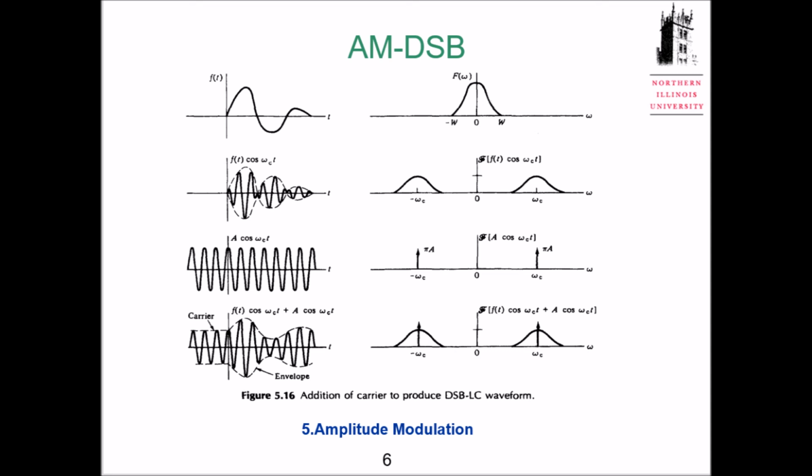We have the picture, we have the figure. If my signal is something like this and its spectrum, F omega, is something like this, like a bell. So I have my signal, the modulating signal in time and in frequency. Here, the signal is mixed with a sinusoid. So here, f of t times cosine omega c t we can find, right? I still have my sinusoid here. However, the envelope is changed according to your message. So this is what happened in time and in frequency. Now my spectrum moved, right? Moved to omega c and minus omega c. Okay, minus omega c is just a concept. We know that there is no negative frequency, right? So if you look at it in a spectrum analyzer, only this side. So theoretically, there is also another band over there.